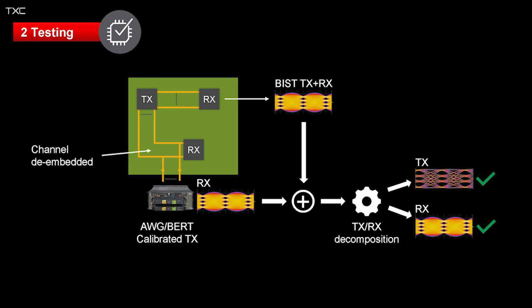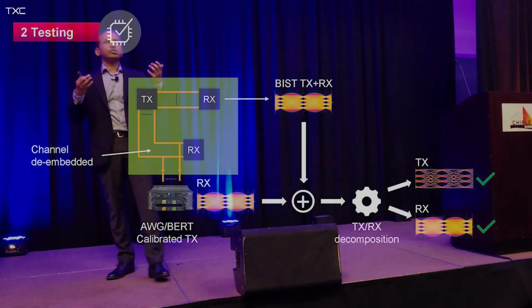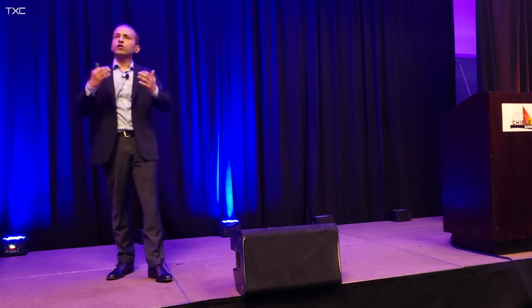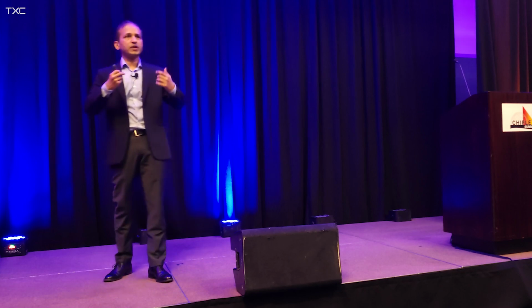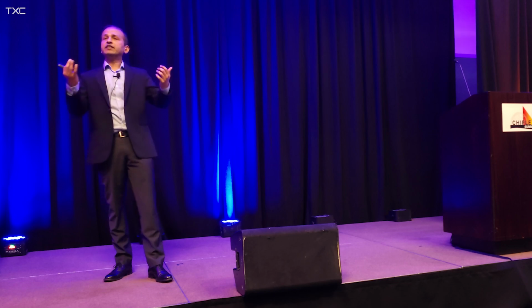So one of the things that you will see is the concept of BIST, or built-in self-test. So a lot of the chiplets come with their own on-chip measurement technologies, and an independent and accurate measurement companion like Keysight can help you improve your BIST. So BIST may be overly optimistic or may not account for all the non-linearities that may be happening at the measurement scale. And so you can calibrate what's happening on the BIST test with a real test coming from an oscilloscope.